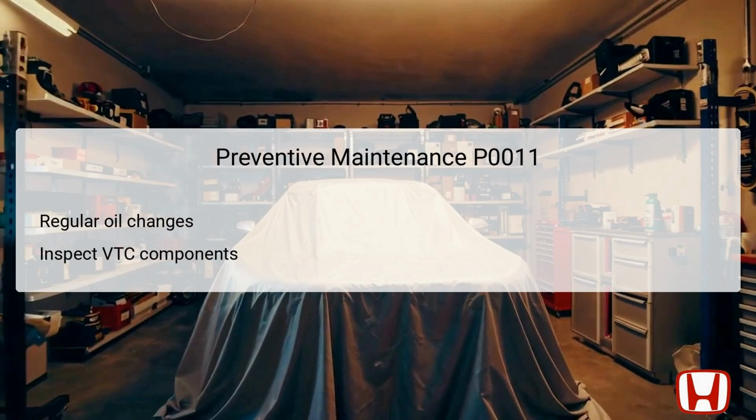and resolved. Preventive maintenance is crucial in ensuring the longevity and reliability of the VTC system in the Honda CR-V. Regular oil changes are significant, since clean oil is vital for the function of the VTC actuator and solenoid. Dirty or degraded oil can lead to clogs in the system, causing components to wear prematurely.